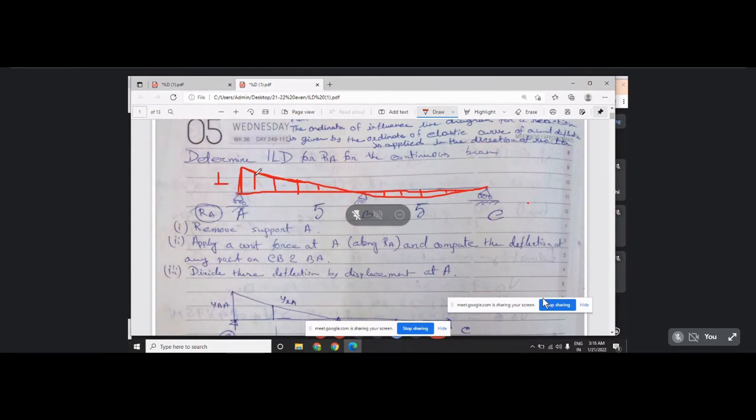to obtain this curve. So this is your deflected shape, this will be 1. Now how will you determine this ordinate? This is quite difficult to see, what should be the ordinate. You do not know what the deflected shape is. In our fourth year class, we put 3 pegs here.